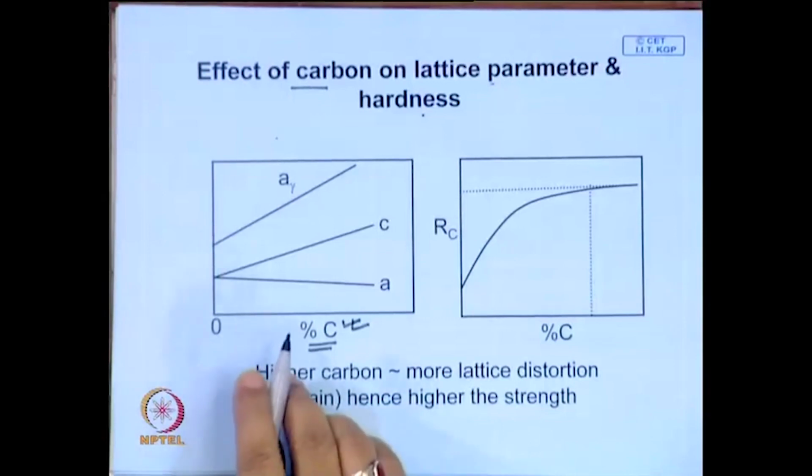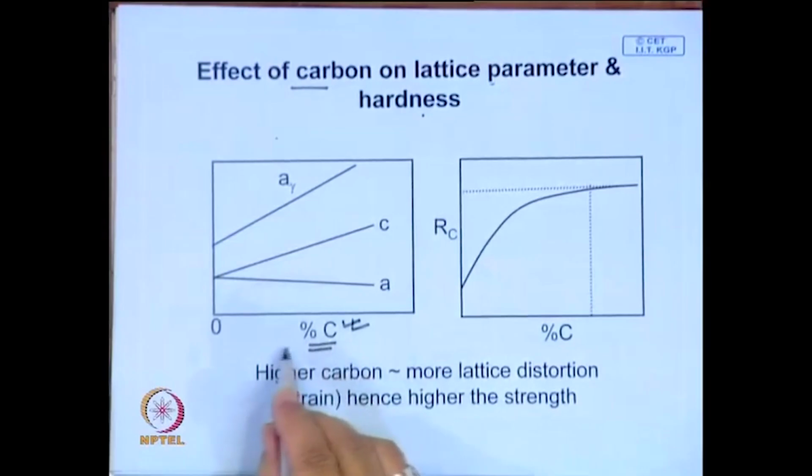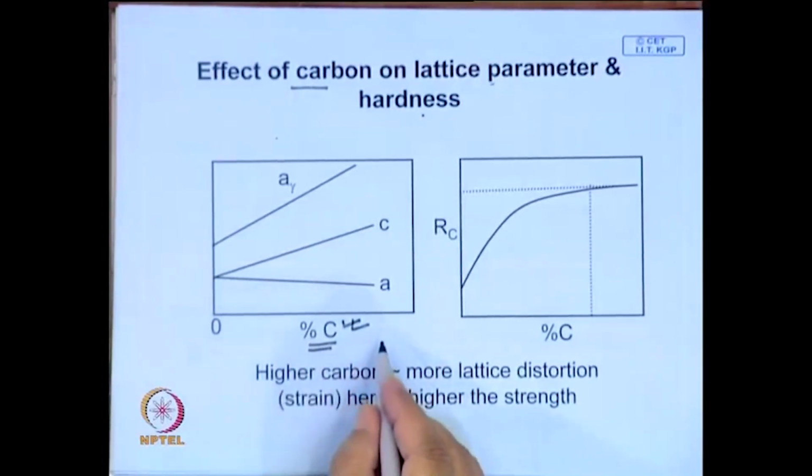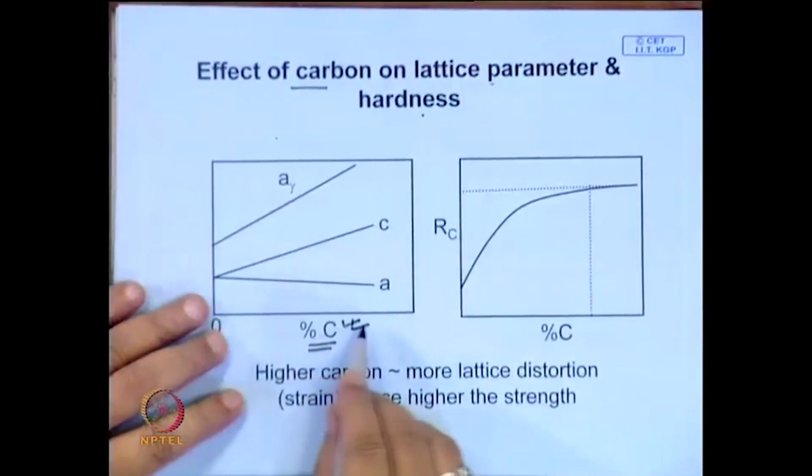So martensite is a highly deformed structure, either plastically deformed or a twin structure, and it is submicroscopic. It is extremely difficult to see the fine structure of the plates or laths.